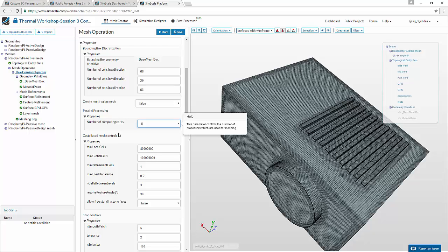So on splitting up the incoming input into a number of processes. Basically, you give the information about the geometry and the mesh settings, and the mesher automatically splits it into various processes as defined here. So when I select 8 processes, it splits up into 8 different processes for computing the meshing process.